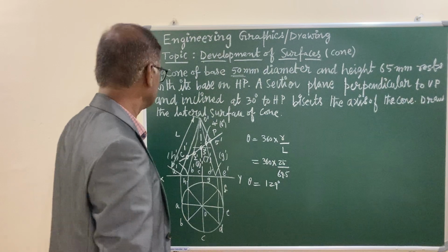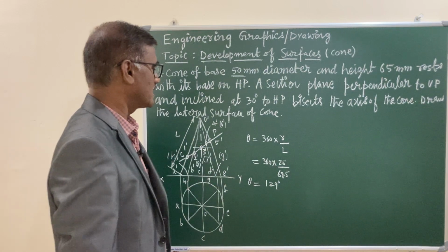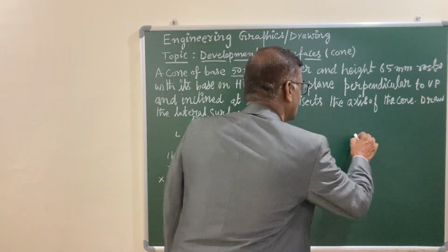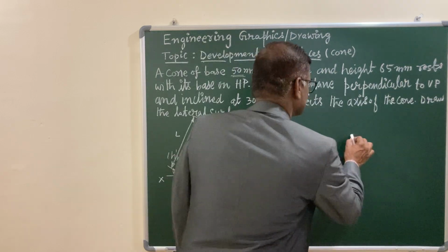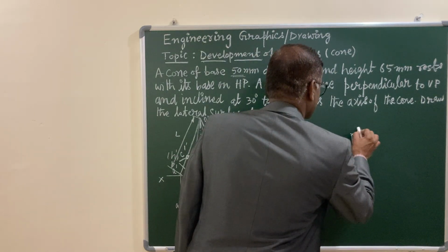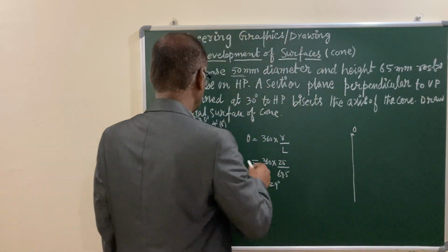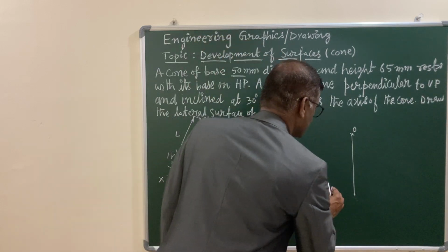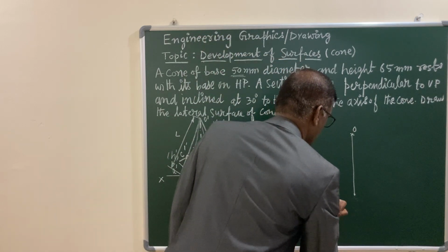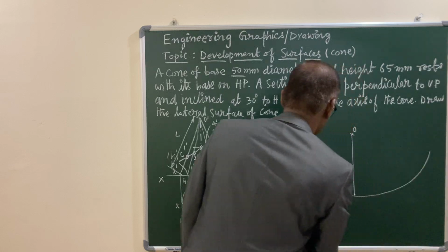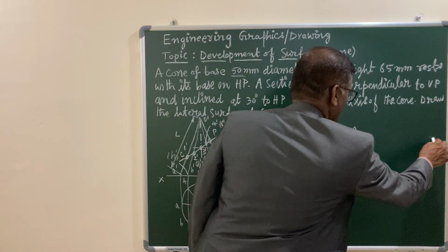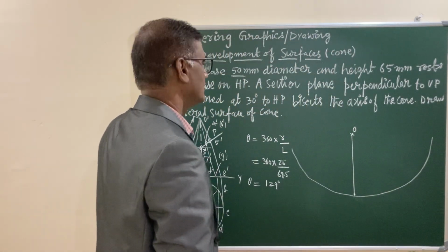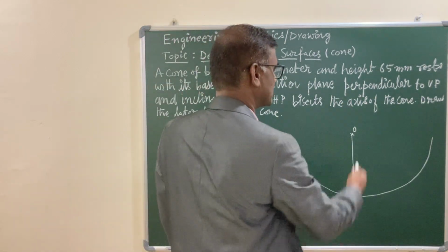Okay, and L, that is 69.5, as radius. Let us draw a vertical line. Here I am taking this as my reference point. Let us call it O, and length is equal to 69.5. With this as radius, draw a circular arc. First you make it approximately the semicircular arc, and after that the unwanted portion you can erase. Now you can make it symmetric about this vertical line.